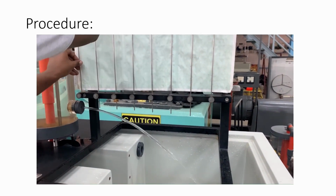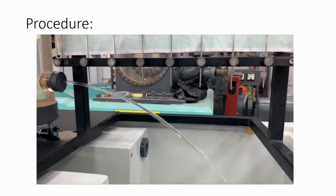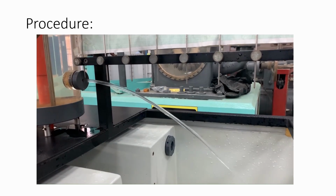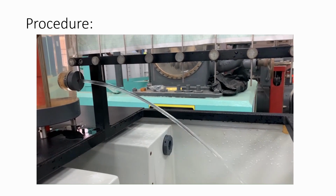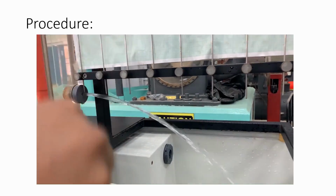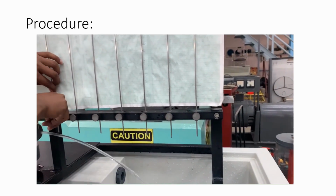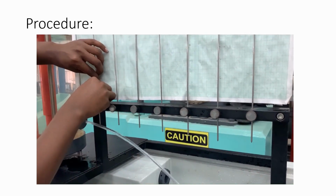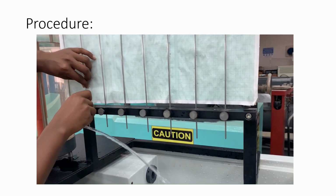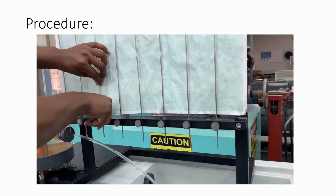Now the next step is being executed, where the trajectory probes are being adjusted to just barely touch the top of the jet trajectory. Here we see the first probe being adjusted, and it is important to know that the probe must barely touch and should not interfere with the trajectory further downstream. The second probe is now being adjusted. Moving on to the third.